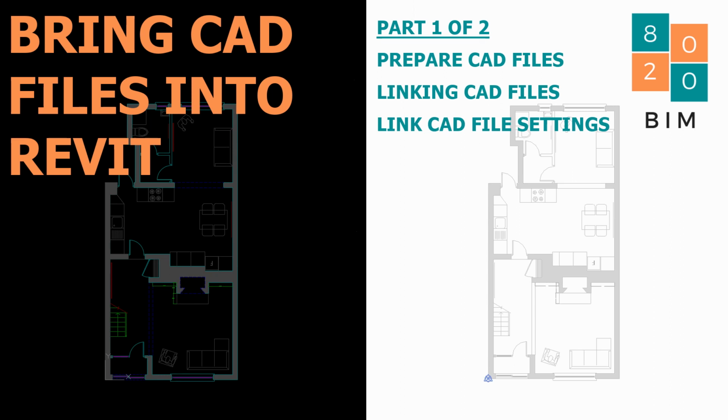And it can be a little bit of a time-consuming exercise in the first instance, but then you have a series of drafting views that you can apply to your project templates or to a standalone project that you can then insert from file, and just have a library that you can draw down from every project going forward in terms of typical 2D details that you may not necessarily be modeling per project.